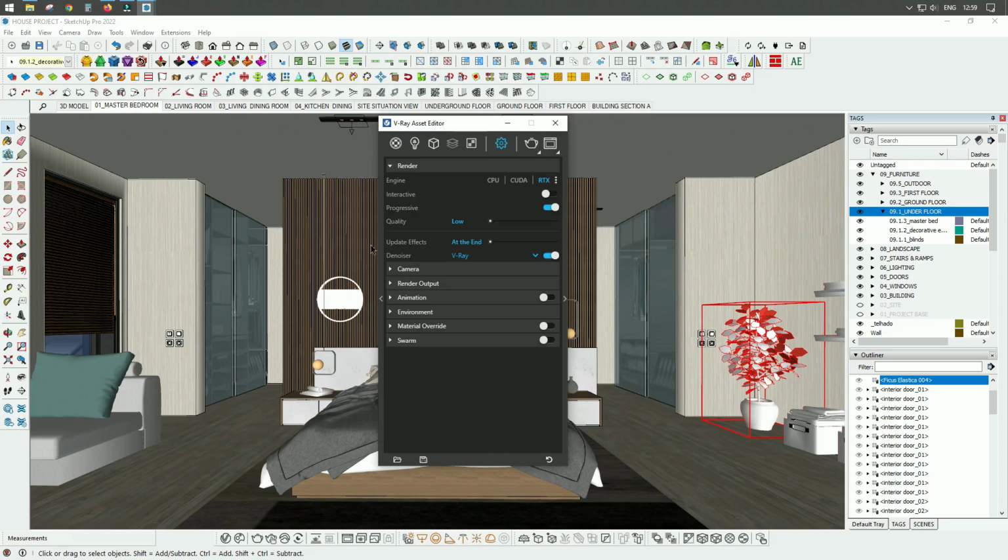these are your render settings actually, and this button here represents the opportunity to make an interactive rendering, to make a cloud rendering, or to export this scene as a file, and by default we have a rendering button here, and the next one is actually your frame buffer that represents a window of your rendering.